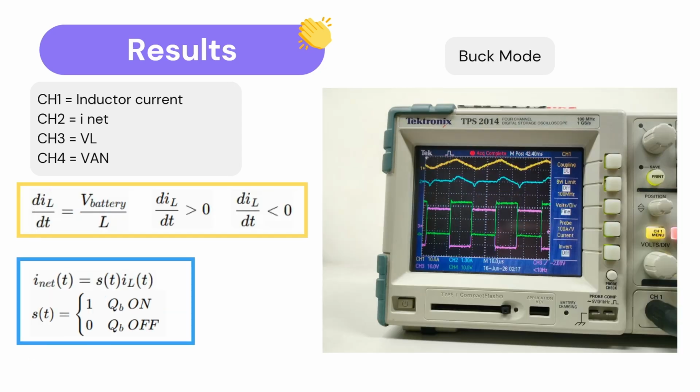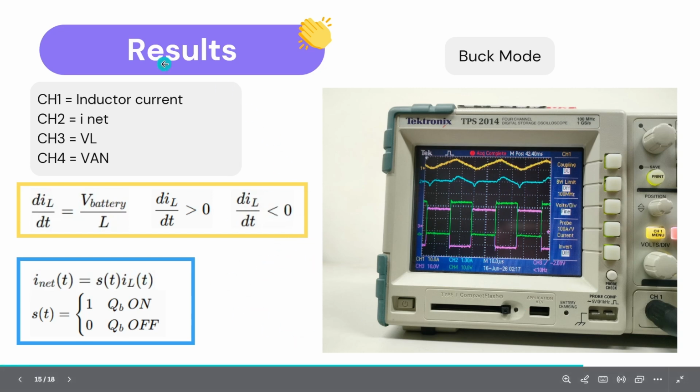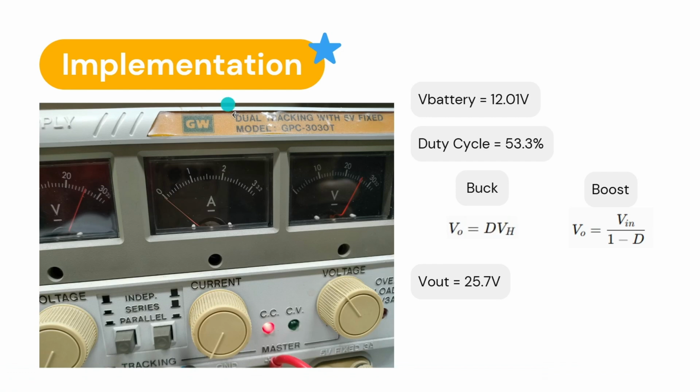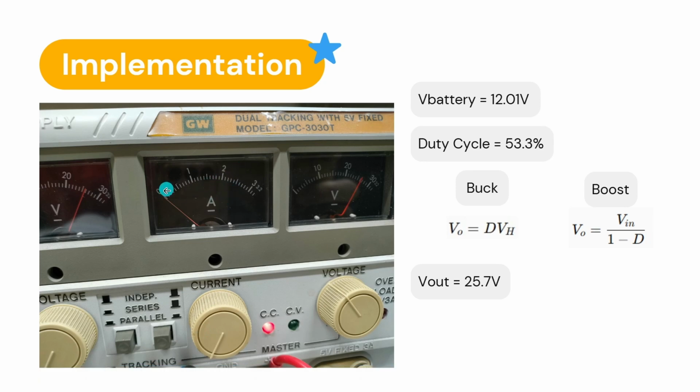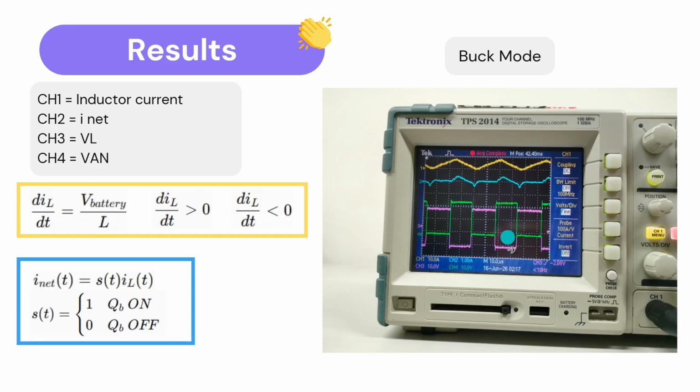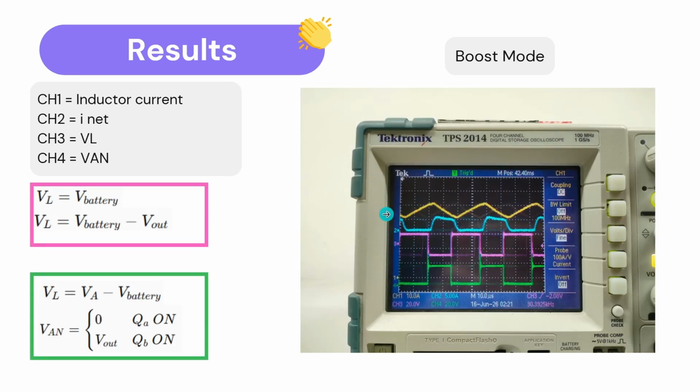And in the buck mode, we have the battery charger. Here in the power supply, we also increase the current to 0.5, 1.5, and the limit is 2. I do this gradually. As I increase the current from the V load, the battery charges faster, and the inductor current ramps up accordingly. So we can see here the voltage getting higher, the current getting higher, and the ground being further from the waveform.